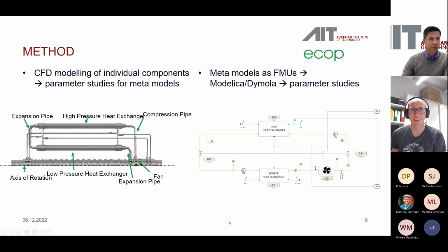So very easy to say, but in the background there are many things to do in Modelica and Dymola to really have it like this. This was just a different variant of our overall model. And we found in the overall model that this could be a problem that does not converge. There was no successful run. Then we tried to change some variables in parts of this overall model, so in the component models. I hope this was clear enough.